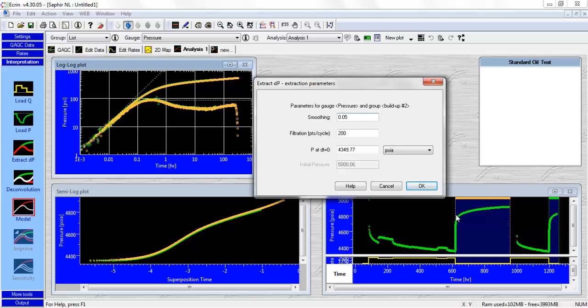Okay, so the pressure at the gauge will no longer be a direct measurement of the pressure at the perforation. So the data won't be reliable for the analysis. It won't be representative of the well and the reservoir. It will only be affected by some dynamic behavior in the tubing, okay, some changes in fluid density.